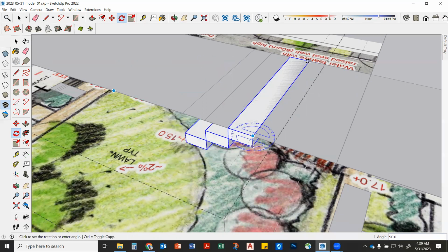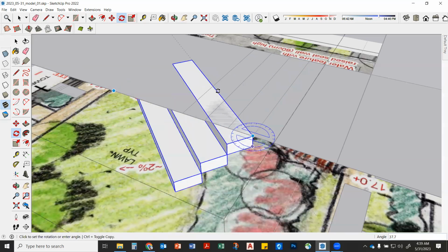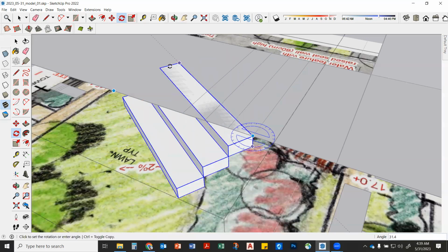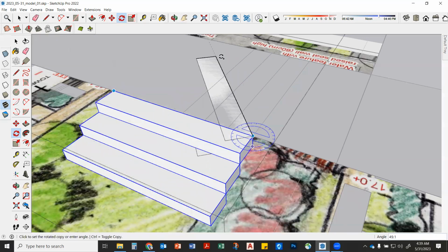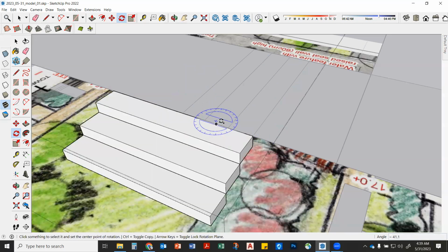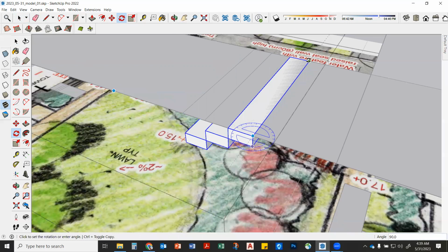Watch, I could come over here and just rotate it around and click right there. But also, the cool thing is there's another option at the bottom. It says Control equals toggle copy. So if I wanted to, I could hit Control, and then I've got 2 of them. Isn't that great? So if I'm doing something, I could actually do multiple copies at certain angles. Oops. Control Y, we're back. Okay, Q, click here, click there where I'm starting, bring it around to there, and we're good.